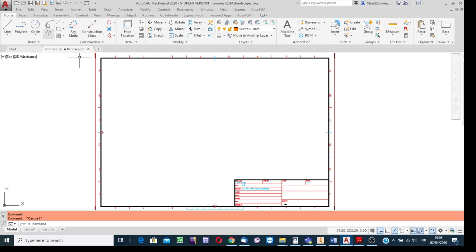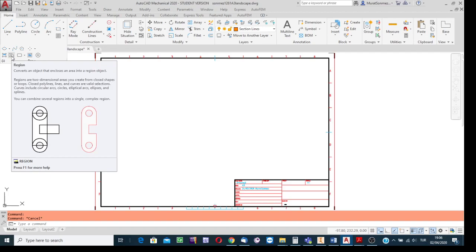Instead of using the polyline facility, if we create the lines using this tool, then when we finish the drawing, we expand the drawing panel with a click, and while clicking on this button, define the area bounded by the boundary lines as a region.